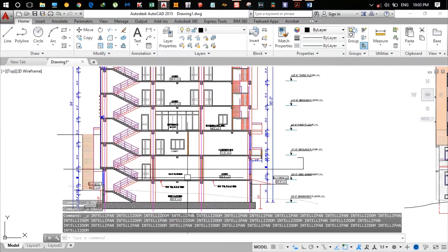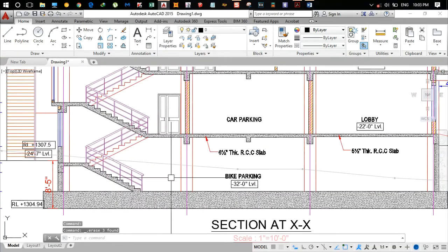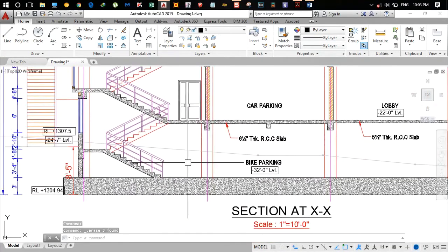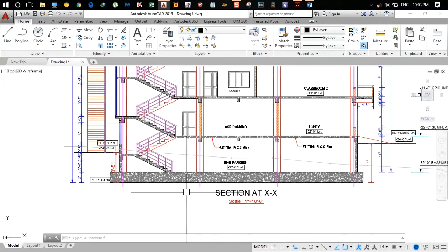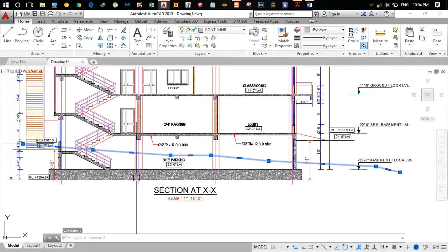Okay, so seismic weight of the building, the rule says that for calculating the seismic weight of the building, you don't have to consider the portion of the building that is below the earth. This is your contour line, this line shown in the diagram. So this is your contour line, and this portion is below the earth. So you don't have to consider the weight of this portion while calculating the seismic weight of the building.